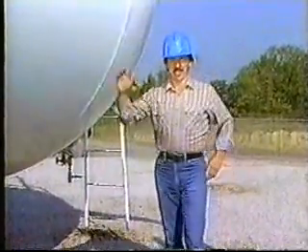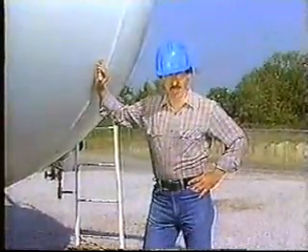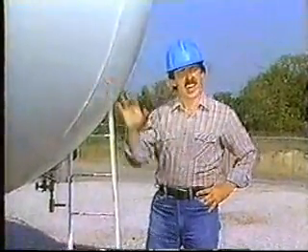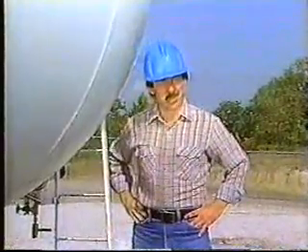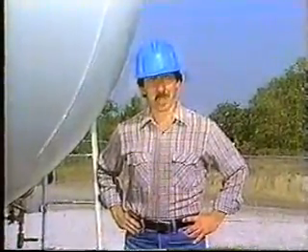Today, a whole industry has developed around NGLs. Because of their importance as a revenue producer, every effort must be made to accurately measure their volume. However, numerous factors can affect the accuracy of NGL measurement. First, solid particles can damage any of the volume measuring devices. Solids can break parts off meters, can upset the movement of meters, and can pit parts of the meters. Usually a strainer is installed upstream of the metering device to remove these solids.